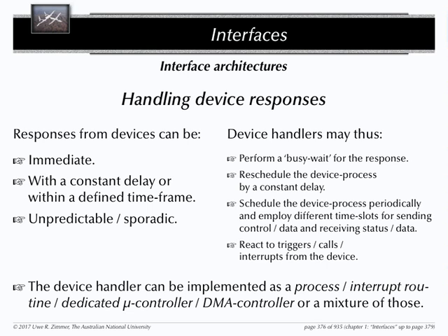Now, on an embedded device and in a real-time world, that's your job. You don't have a non-real-time operating system doing that somehow for you. You have to actively control it. You have to make a decision. Will I be standing by? Will I be staring at this I/O line until something comes back? Will I suspend myself? How long will I suspend myself? Do I want to be reawakened after some time? Do I want to be reawakened after a specific event happens? Those decisions have to be made by you now.